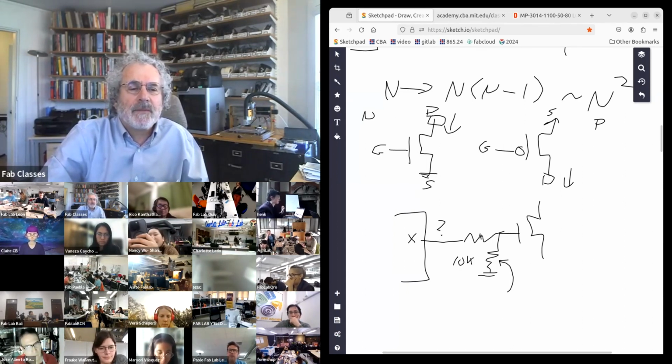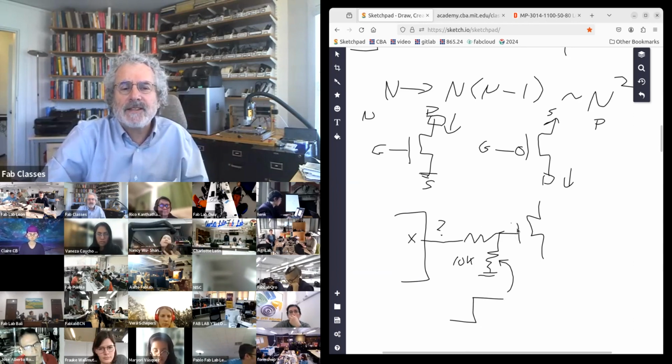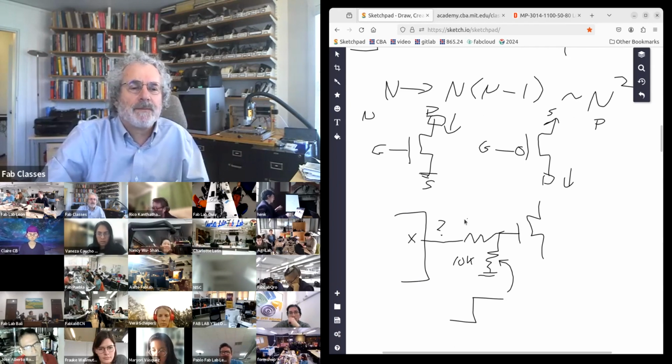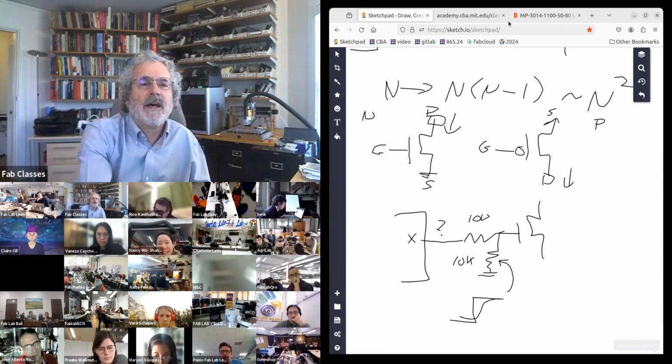And again, this resistor here: when you turn on the MOSFET, you slam it on, which can make electrical noise and a big current surge. The MOSFET acts like a capacitor. So this is a fairly small resistor. It depends on the application. And the job of that resistor is to slow down the transition so it's not as noisy.